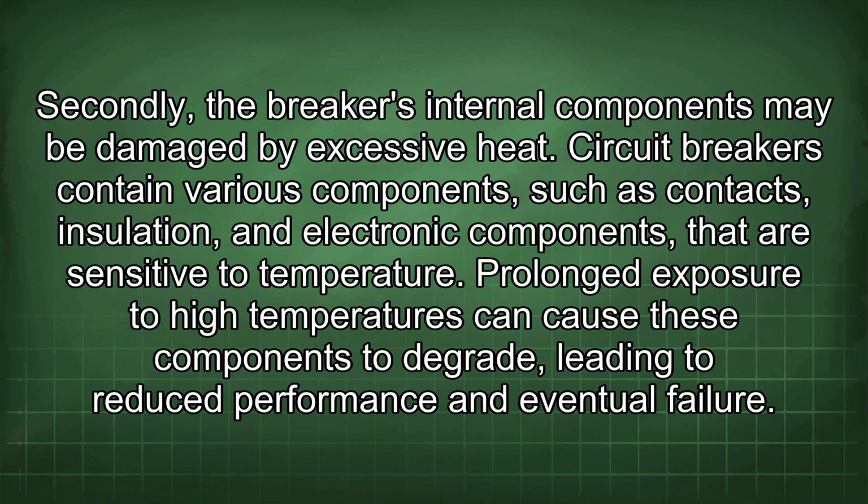Secondly, the breaker's internal components may be damaged by excessive heat. Circuit breakers contain various components such as contacts, insulation, and electronic components that are sensitive to temperature. Prolonged exposure to high temperatures can cause these components to degrade, leading to reduced performance and eventual failure.